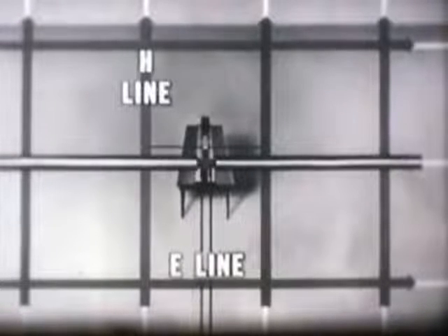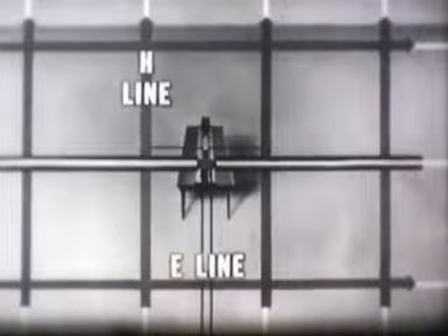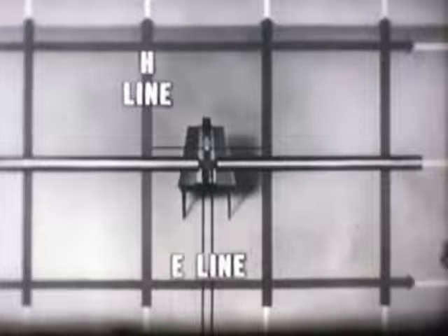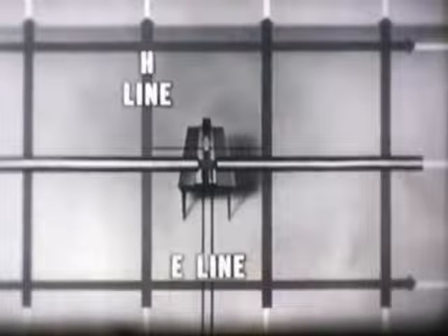In order for a signal to be received at maximum intensity from this wave, the H lines of the wavefront must cut the receiving antenna at right angles. Therefore, the polarization of the receiving antenna must also be considered. In this case, the receiving antenna must be horizontal and at right angles to the H lines of the wavefront. The transmitting and receiving antennas are now parallel and broadside to each other. This broadside position is necessary because of the nature of the radiation pattern of the half-wave antenna.